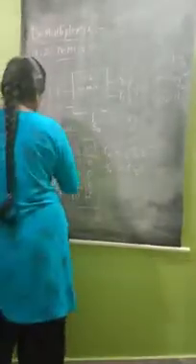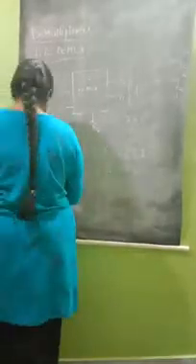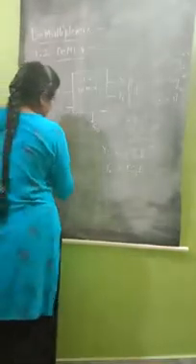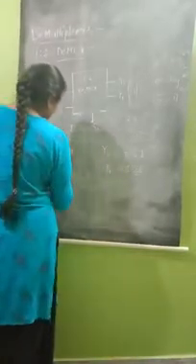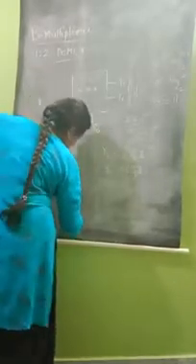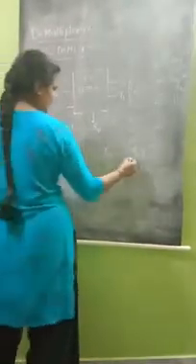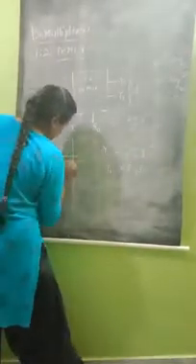So we can draw the logic design of the 1:2 demultiplexer by using these two equations. Here enable E, S0 and I. This is the complement of S0 and this is I. So E, S0 bar and I.